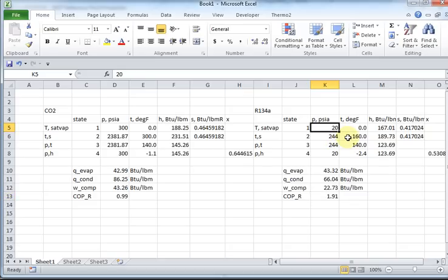Let me do this. If I have a leak in the evaporator, the pressure is 20 psi in the evaporator. Is the fluid going to come out or air going to go in? Refrigerant's going to come out. But there's only a 5 psi difference. So it's not going to be a bad leak, you know what I mean? Not like spraying and killing people. But look at this. I got 300 psi. If I have a leak there, it's really going to gush out, right? And now this is a lot higher pressure right in here. I mean, that's ridiculously high pressure. All right? So this is reasonable pressures.